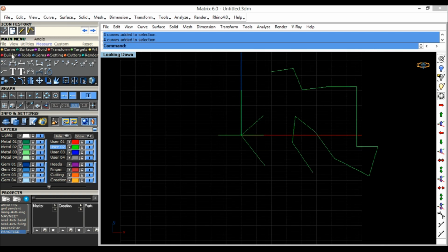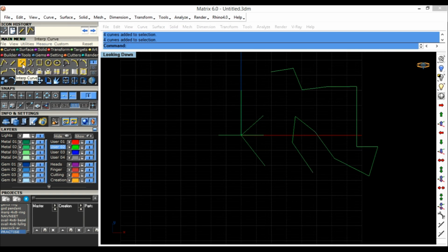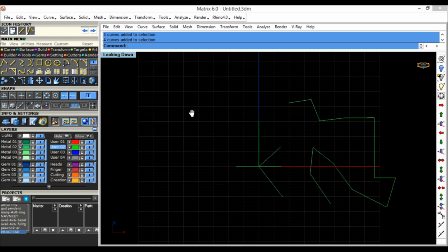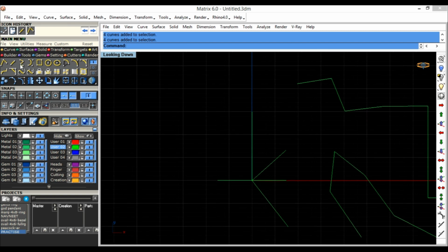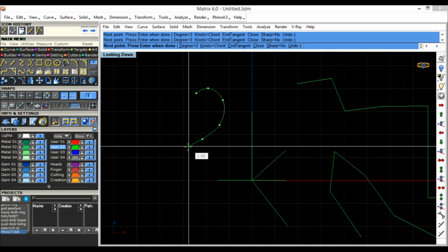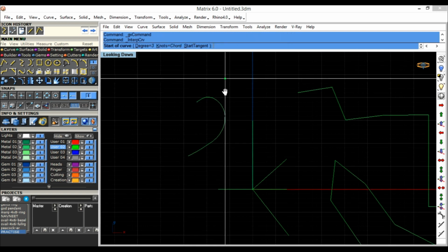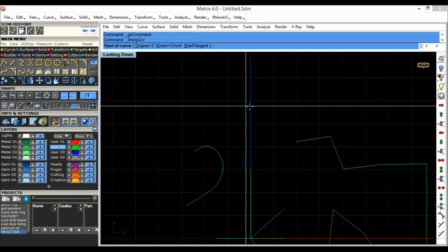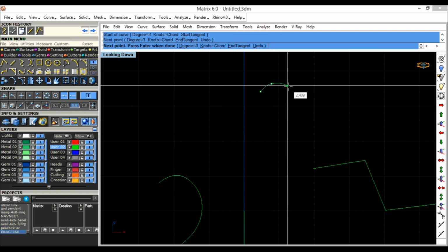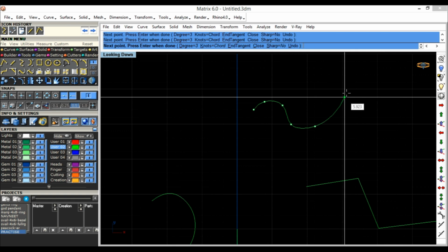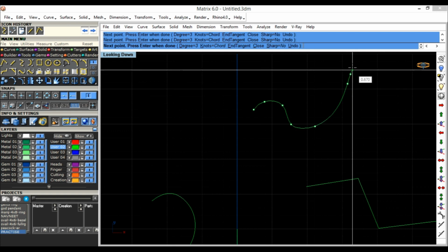Next command we go for is interpolate curves. Interpolate curves is for drawing smooth lines. Any curve shape if you want to draw, you can draw it accordingly. See, right click, if you first take the command, then click where you want, how you want it. Okay, go on clicking. How much bigger or how much shorter? The more shorter you click, the more tight it will be.